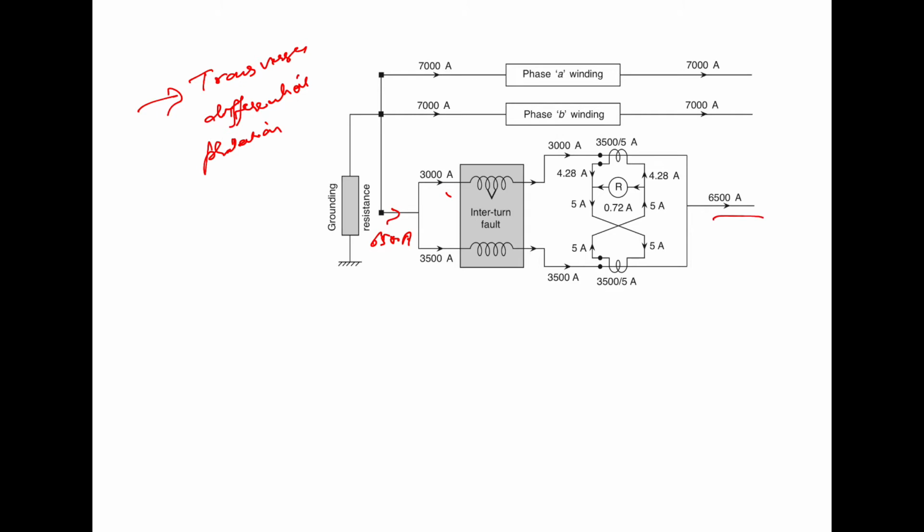And if suppose we are using the differential protection here in these two parts, then you will see that no spill current is there, and as a result the longitudinal differential protection will not work in that very case. So longitudinal differential protection will not work.